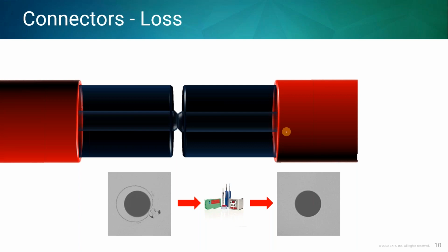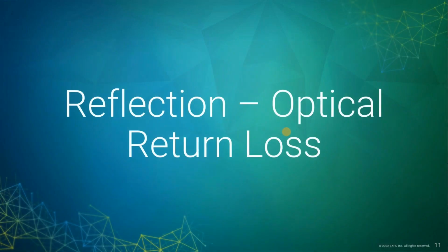And I cannot stress enough the importance of having good cleaning practice. So inspecting and cleaning your connectors. This is the biggest issue that we run into. So I did a video once. It's like a 15-minute video somewhere. I'm sure it's buried on YouTube. I know it's buried on YouTube. That I call cleaning connectors with an OTDR, which is basically troubleshooting contaminated or bad connectors using an OTDR. And we'll cover a portion of that here today.